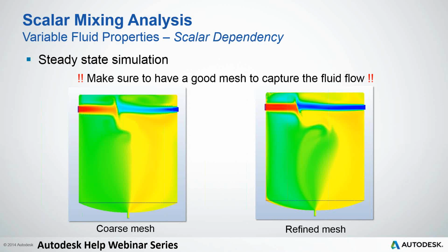And as I told you, it's very important to create the mesh regions in the positions where you have a high gradient or turbulence. As you can see here, this is the coarse mesh that I made, and this one was when I created a mesh region over here, a cylindrical one, and a cylindrical one over here. You can see how the refined mesh showed a much better fluid flow in comparison to this one. And these are the scalar analysis results.